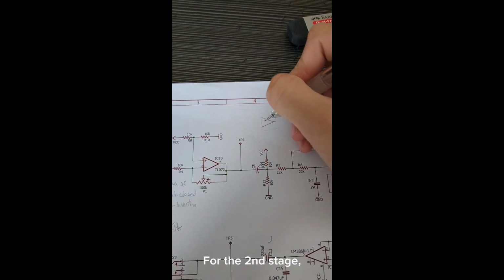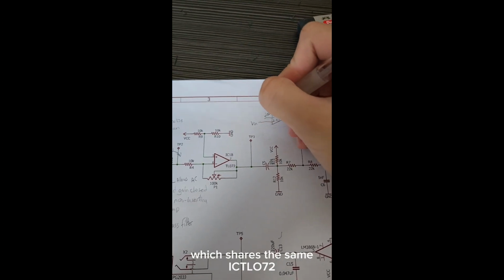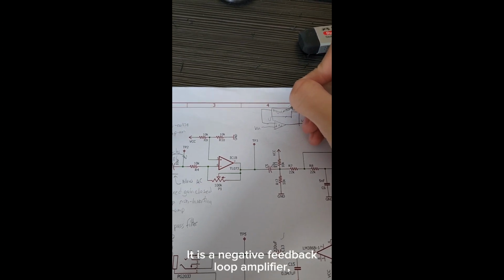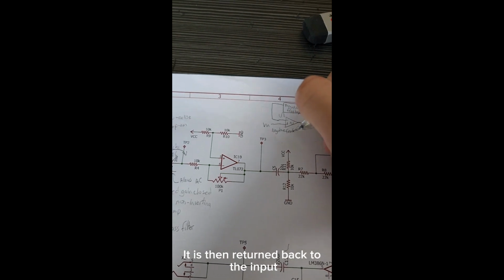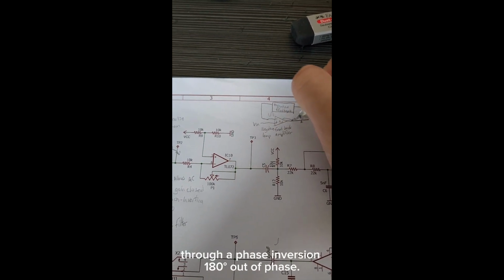For the second stage, we'll be using IC1B, which shares the same IC TL072 with IC1A. It is a negative feedback loop amplifier, where a fraction of the output is subtracted from the input. It is then returned back to the input with a phase inversion, 180 degrees out of phase.